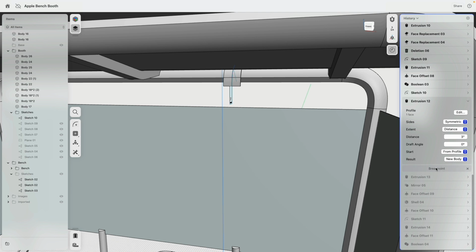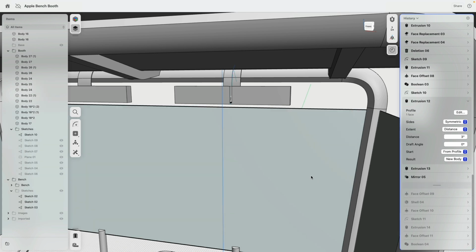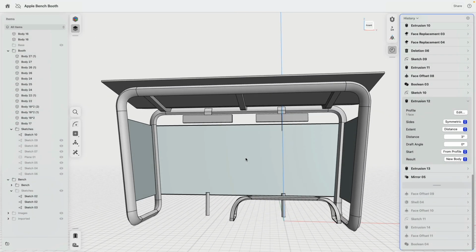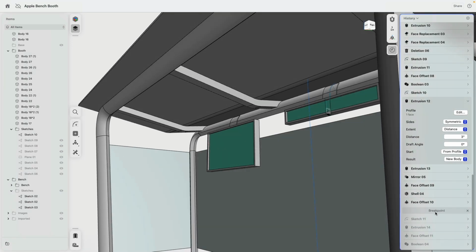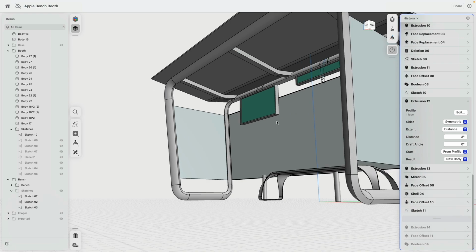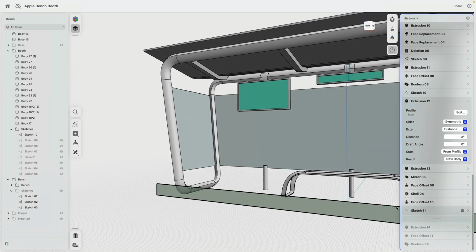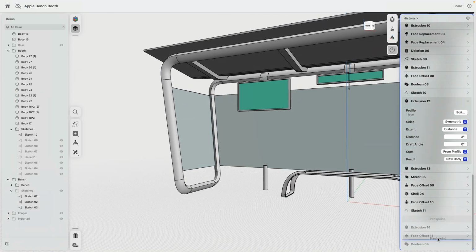Okay, perfect. So that's kind of a metal piece that's folded over. There is our box, this box, and this piece I mirrored over. And then I simply use direct modeling, push this one down, shell both boxes, and move the interfaces a tick forward. Did another sketch, that's for the base.